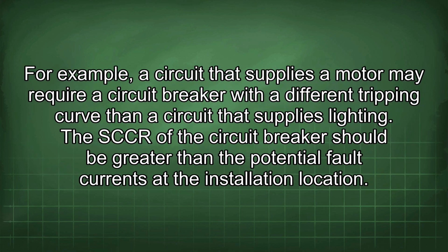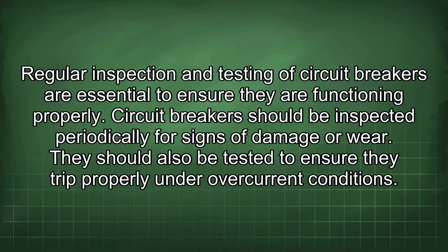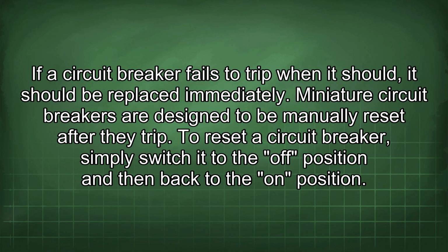For example, a circuit that supplies a motor may require a circuit breaker with a different tripping curve than a circuit that supplies lighting. The SCCR of the circuit breaker should be greater than the potential fault currents at the installation location. Regular inspection and testing of circuit breakers are essential to ensure they are functioning properly. Circuit breakers should be inspected periodically for signs of damage or wear. They should also be tested to ensure they trip properly under overcurrent conditions. If a circuit breaker fails to trip when it should, it should be replaced immediately.